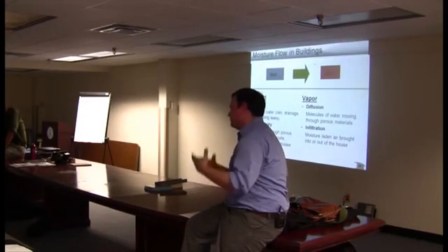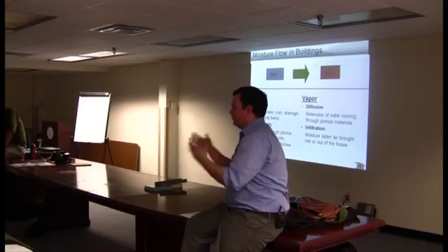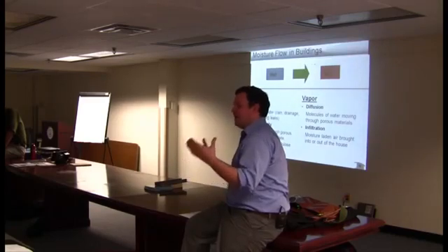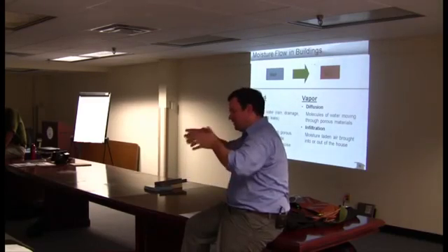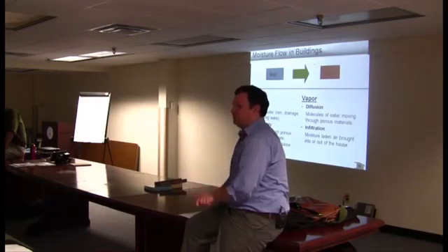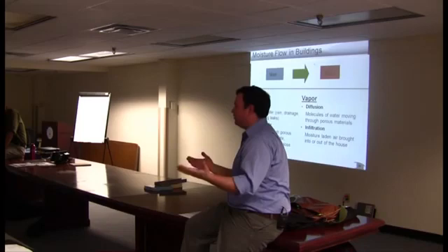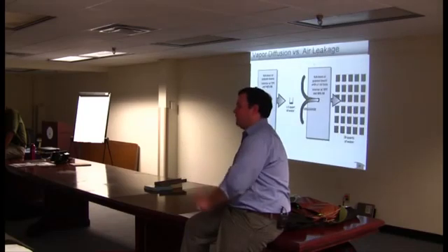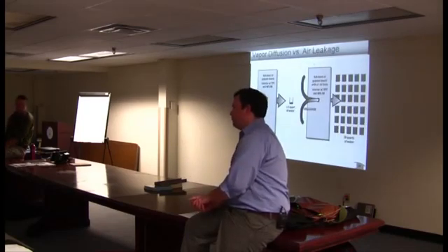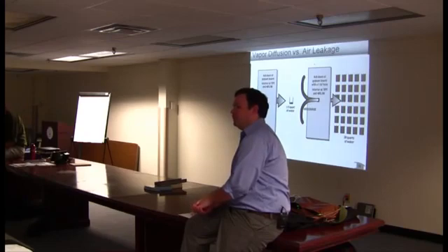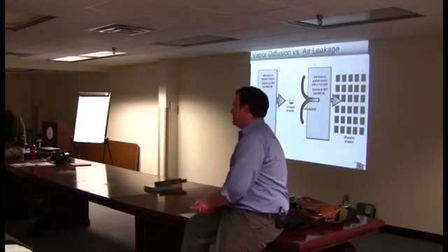Diffusion is basically air movement at the molecular level. It takes a long time, and it's about the air basically diffusing through building assemblies. Infiltration, on the other hand, happens really rapidly, very quickly, and we're actually able to bring large volumes of moisture unwantedly into a building because of infiltration.